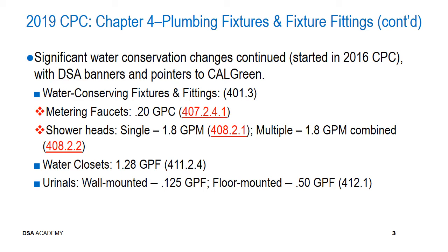So when a project inspector is reviewing submittals for any water using fixtures, whether it's metering faucets, shower heads, water closets, urinals, lavies, sinks, any type of water use fixture, you need to make sure that the flow characteristics for each of the fixtures comply with the code.